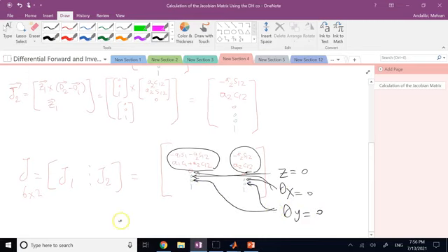And what about theta z? Well, in this case, clearly theta z is theta 1 plus theta 2. So if you take partial derivative, you will get this. So you see the derivative of omega z with respect to theta 1 dot is 1. With respect to theta 2 dot is also what? 1. So this is the 2 degree of freedom planar arm, the Jacobian of it, if you consider everything, okay?